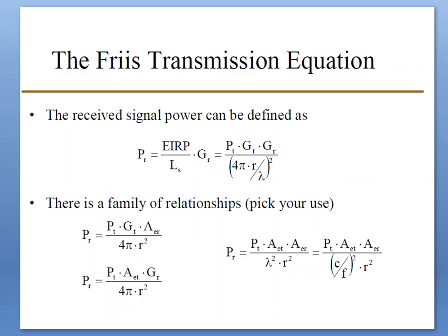The dependent variable is the receiving power PR, and the independent variables involve parameters such as transmitting power, antenna gain, antenna area, wavelength and the range. Suppose we ask the question, how does the receiving power vary as wavelength decreases or increases, with all other independent variables remaining constant? It appears that the receiving power and wavelength are not related at all. From the above equations, PR appears to be inversely proportional to the wavelength squared, and also PR appears directly proportional to the wavelength squared. Is there a paradox here?